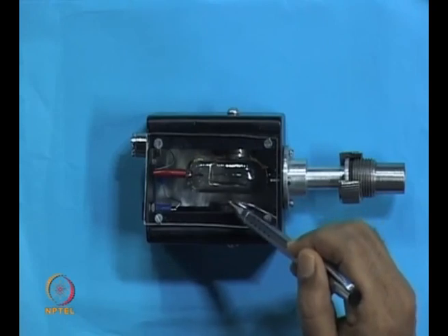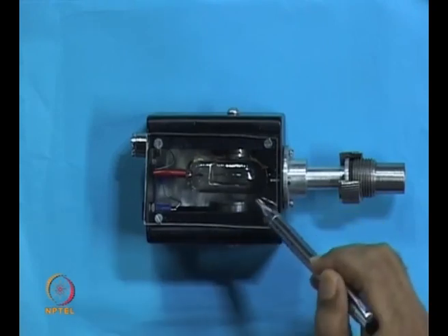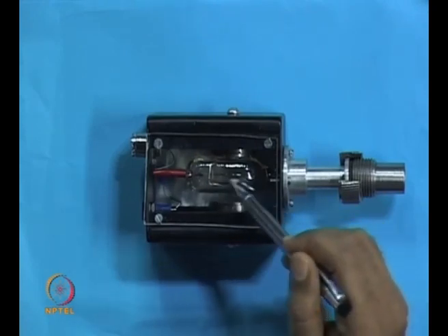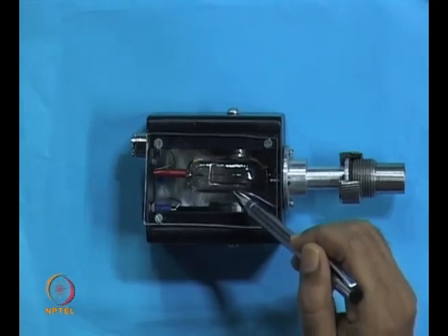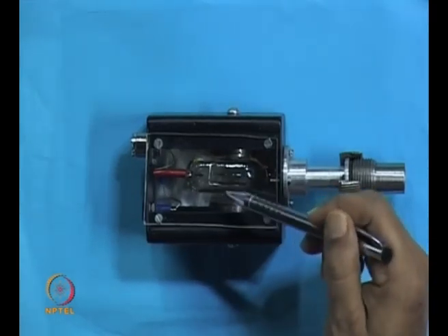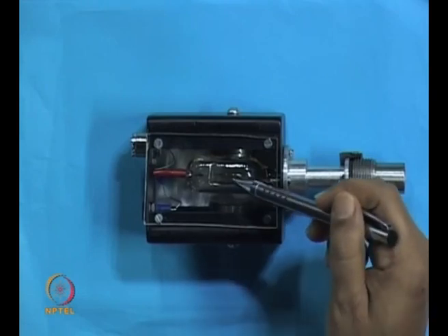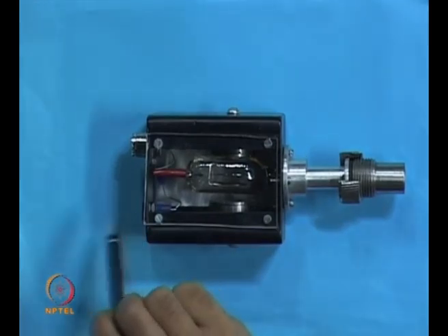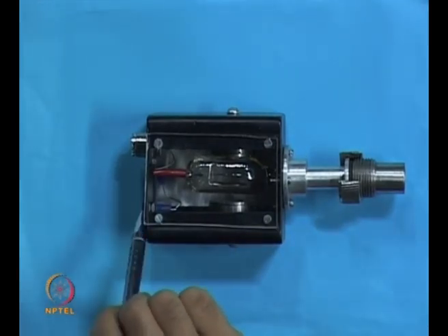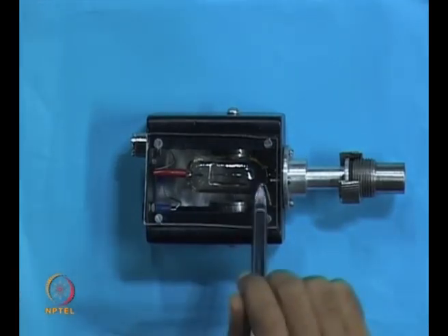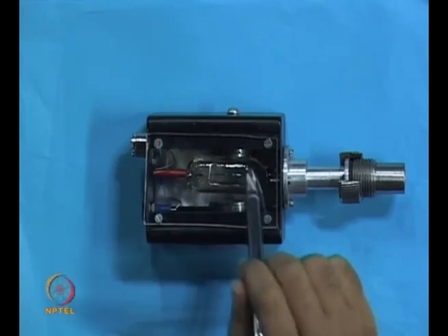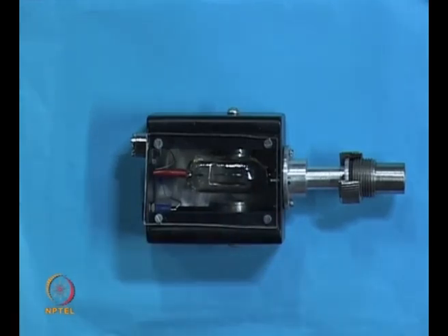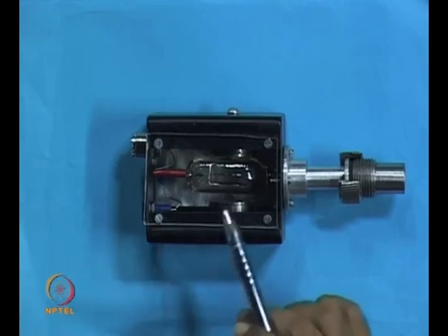This electron, while traveling from cathode to anode, will ionize the gas molecules, and depending on the ionization current produced because of the electrons striking the molecules, this ionization current will be fed to the gauge, which is calibrated so that we know the residual gas pressure over here. And this is the way the Penning gauge works. This is the way the cold cathode ionization gauge works.